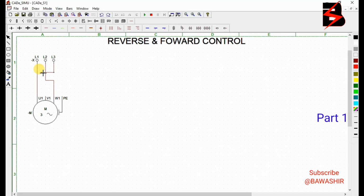Instead of taking it to W, we shall take it to V. Are you seeing? We have interchanged. Line 1 we have given it W, then line 3 we have given it V. So when we try to run this motor, we shall see that it has changed direction. It is now running anti-clockwise.